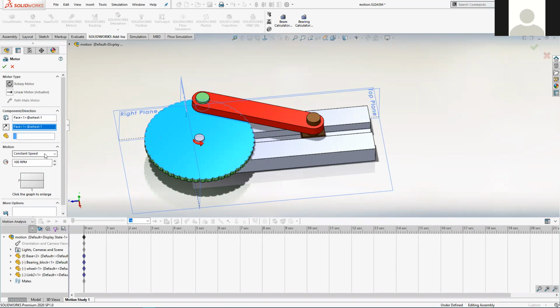Now, if you run this as a thought experiment, there's a fraction of a fraction of a fraction of a second where the simulation starts and then the motor suddenly is at 100 RPM, and you get all sorts of strange shock loads happening that maybe weren't intentional. Some of the results that you end up looking at look horrendous, and the stresses in the part are well beyond what you expect them to be.